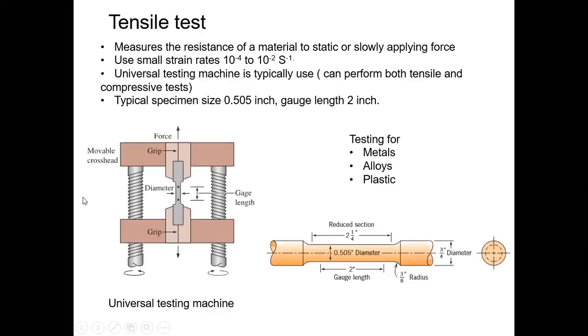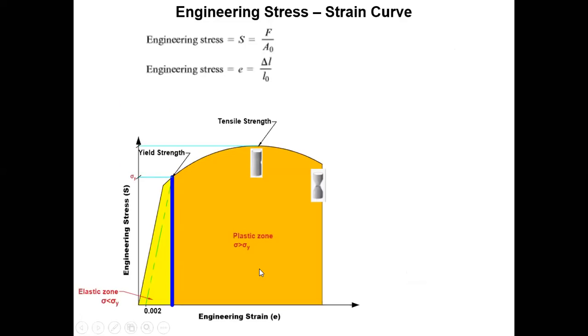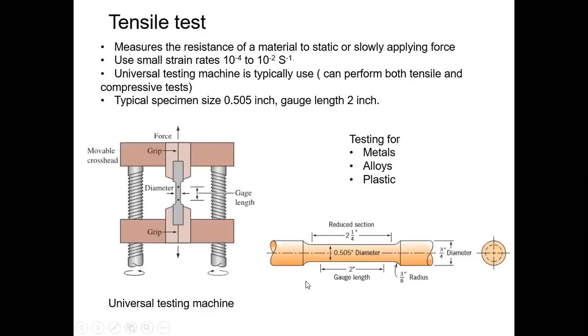It will show details about how to conduct a tensile test, most probably not using that benchtop machine, but using a universal testing machine, right? So I told you initially we have a specimen, right? We consider this as the length of a specimen because under the applied load, the break of this specimen will happen at the weakest cross section. That means minimum cross section locations, right? So we know the initial diameter and the initial length of the specimen, right?